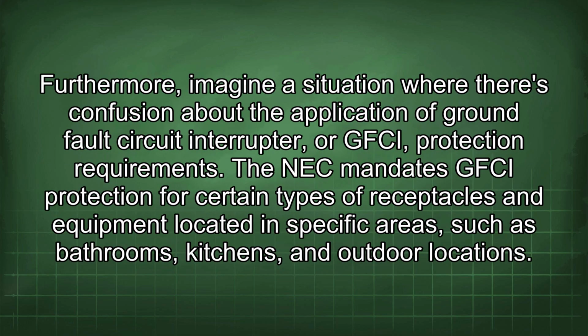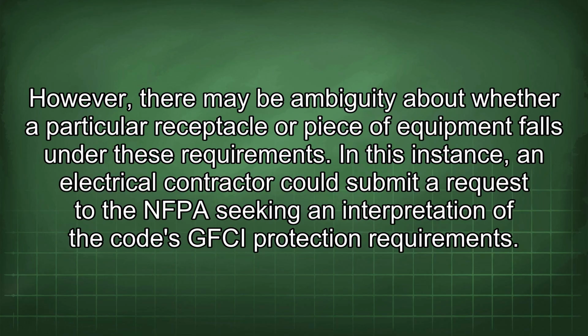Furthermore, imagine a situation where there's confusion about the application of ground fault circuit interrupter, or GFCI, protection requirements. The NEC mandates GFCI protection for certain types of receptacles and equipment located in specific areas, such as bathrooms, kitchens, and outdoor locations.